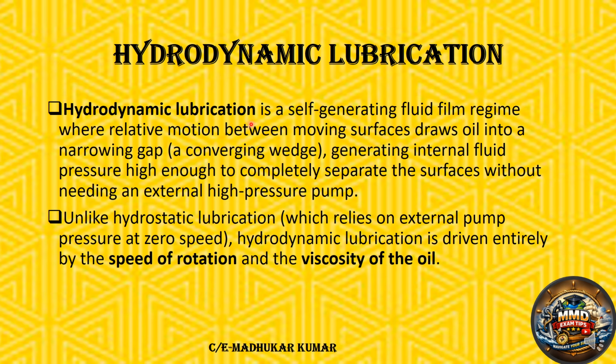And it happens due to the relative motion between the moving surfaces. This is the most important. Hydrostatic is static. There is no motion at rest. But when we talk about hydrodynamic, we have a relative motion between the moving surfaces. It draws oil into the narrow gap and creates a converging wedge. I will show you the diagram also. Don't worry, I have that part also.